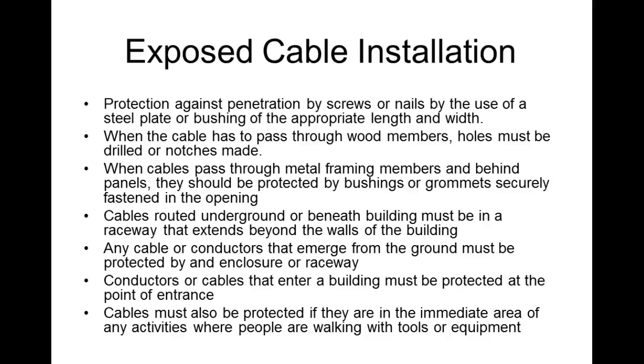So usually, especially when they're sheetrocking, you should not have any problems if the cables are running right, because what they're supposed to do is drill those holes in the center of the 2x4. In fact, you can go down to Lowe's. We do so much wiring through walls in residential. You can buy 2x4s with the holes already cut through to run those cables through. If not, then you've got to drill them in there yourself.